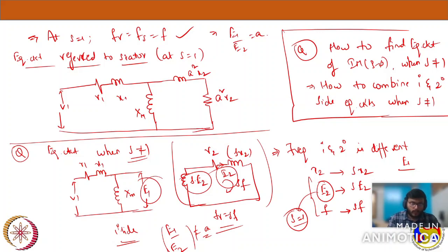Yeah, under root of, exactly. So exactly correct. That's what if you want to calculate the RMS value of rotor current under this frequency SF, it's nothing but my voltage in the secondary rotor circuit, SE2, divided by the equivalent impedance in secondary, that is nothing but the under root R square plus SX2 whole square. Now this is what my current. So this is a very important point.